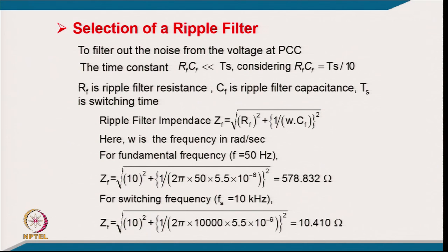When you take the square, it becomes quite a quarter, and the resistance you can call it a quarter. So, its loss will be hardly typically 10 multiplied by 1/4, so around 2-3 watt loss, irrespective of the rating, whether you are designing this UPQC for 50 kVA or 100 kVA or so. But that improves the voltage profile, because all the switching harmonics get sucked into this very low impedance of 10 ohm, but it does not have much higher energy associated with it.